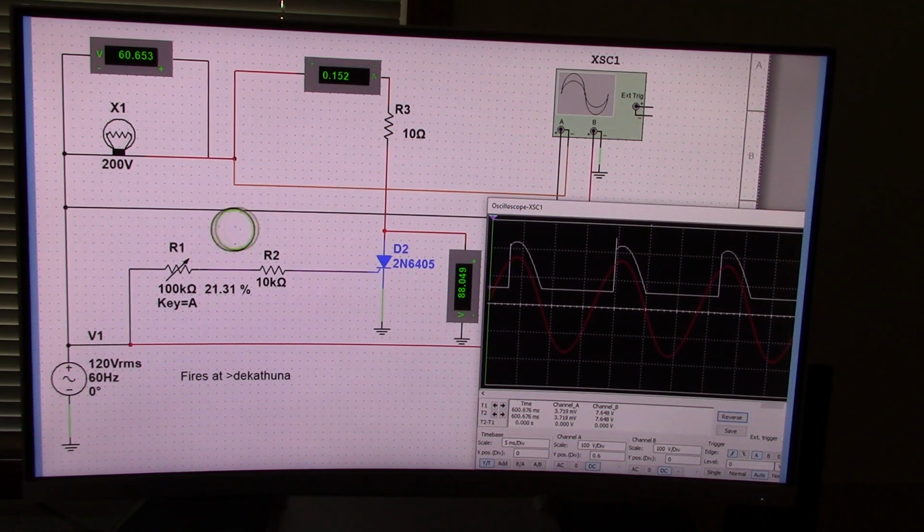And we are going to do a couple of labs on this. I also have a meter up here which measures the voltage. When you're putting these meters in, make sure that you convert them to AC, because these are AC voltages we are talking about, not DC. I think by default these may come up as DC, so make sure that you change these to AC. If not, you'll get some strange answers.